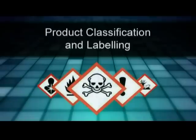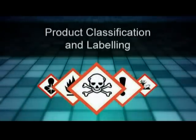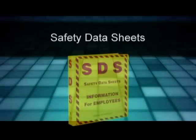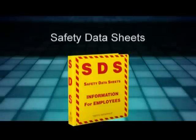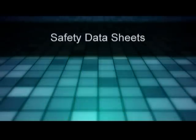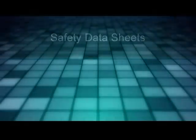1. Hazardous material container labels supply basic information about the product, along with pictograms that highlight the potential dangers. All containers of hazardous materials must be properly labeled. 2. Safety data sheets, or SDSs for short, contain comprehensive information about hazardous materials, including their content and/or ingredients, directions for proper use, correct cleanup and first aid procedures. An SDS must be available to workers for every hazardous product that is used.